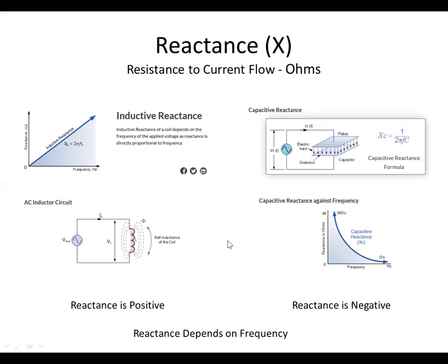That means if we're clever, we can use those two devices to do some pretty neat things. I think I failed to mention that the formula for the capacitive reactance is 1/(2 times pi times the frequency times the capacitance). And just as it was in inductance, 2πFL, this is 1/(2πFC). The pi and the capacitance are all constants for a particular capacitor, and the only thing that you change is the frequency.